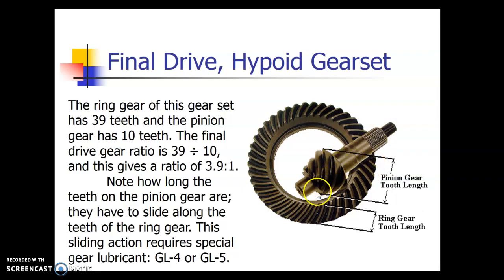So again, here's a breakdown picture. Typically, it looks like a Ford 9-inch has that front bearing on that pinion gear. This helical spiral pinion gear is going to come in and transfer power from the drive shaft. So the drive shaft comes in to the yoke, splined right here. It's going to spin this pinion. This pinion spins this ring gear. The ring gear again spins a carrier, and so on and so forth.